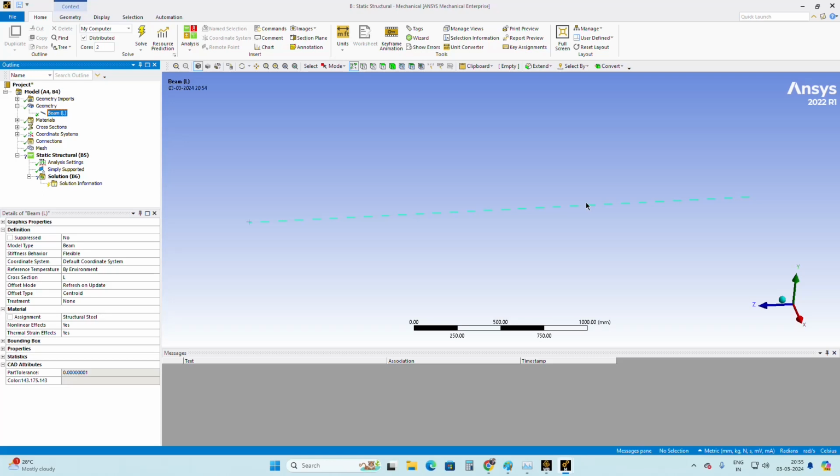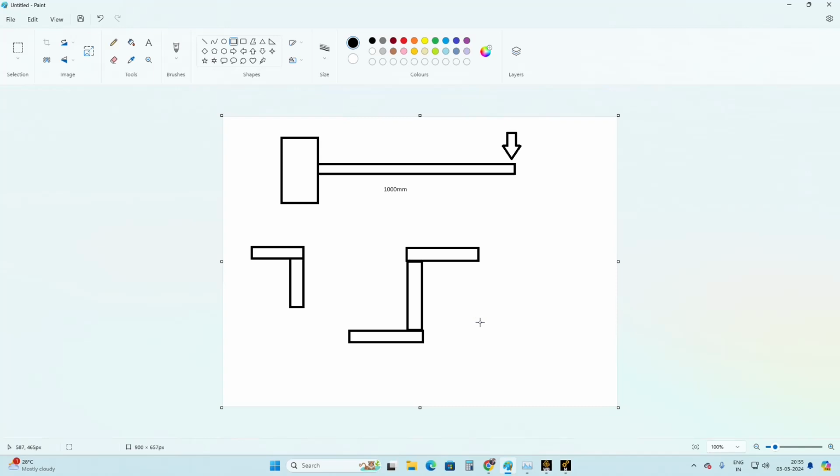When you solve a structural engineering problem like a civil engineering problem, we encounter a lot of beams. There are not only two joints, multiple joints will occur while solving a truss problem, or not only truss, a bridge problem and all. In one joint there will be multiple connections. So for that you have to give the end release. End release is the one condition you have to define for the beam element. For example, consider one line is from here and another line is here, and this type of beam is here like that.